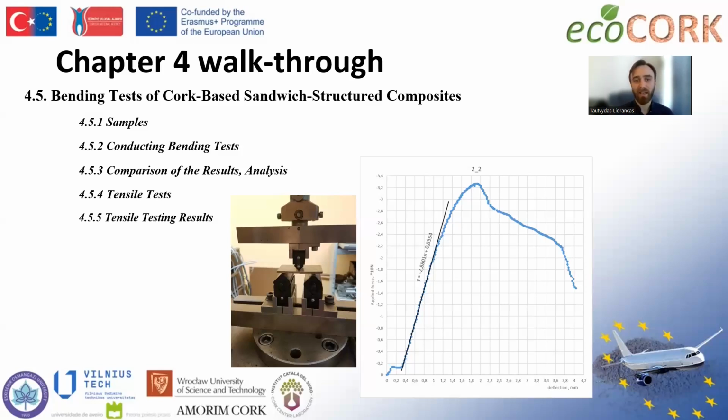The core material doesn't impact the tensile strength of the sandwich plate. If we compare cork material filler and foam material filler, it showed very similar results. And if we compare different grain sizes, all the results were also very similar.